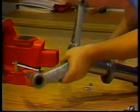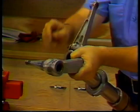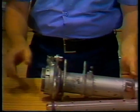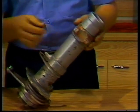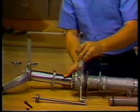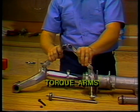Oleo struts are equipped with either an axle or axle attachment at the lower end of the strut. Connections are also made at the upper end of the strut for attachment of the strut to the aircraft. Torque arms are attached to the cylinder and the piston to maintain the proper alignment.